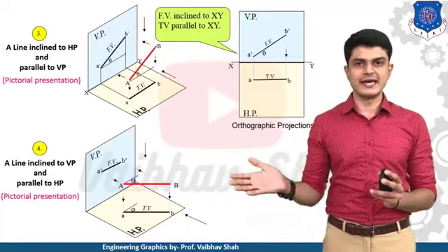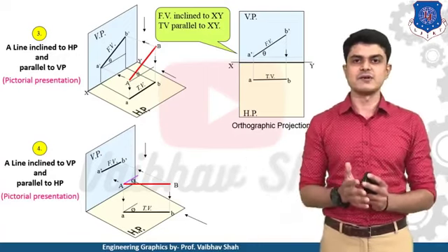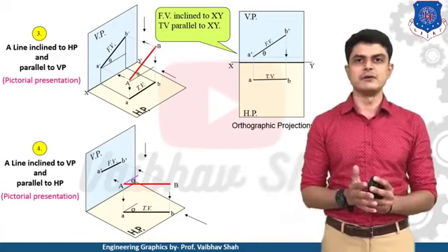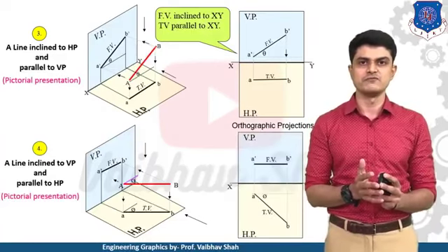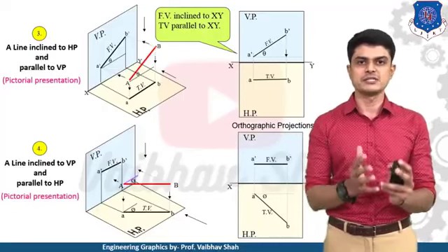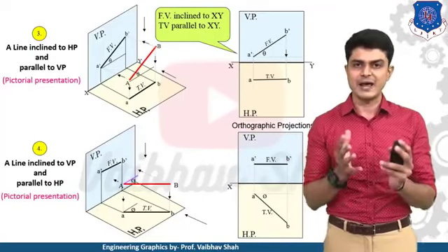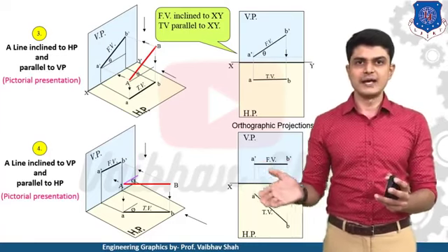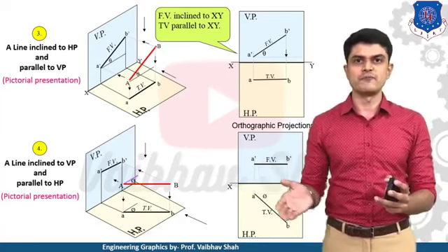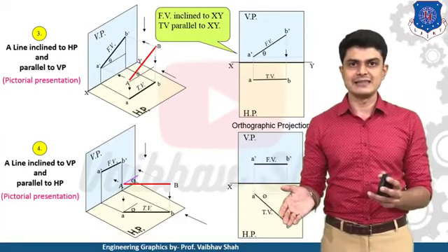So now this is once again a 3D representation of your orthographic projection of lines. So let us convert it into 2D clearly understandable views which you need to show in your examination. So let us draw these two-dimensional views. So what you will do is you will first draw one straight XY line. Then you need to draw this inclined line of true length. You can call it the top view because it is resting on HP. So AB would be your line length.